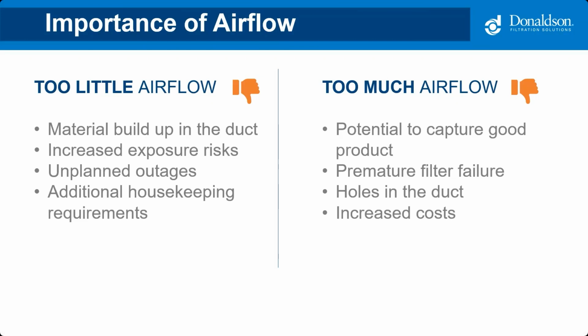Now, if you have too much airflow, you have the potential where wherever your hood is, whatever dust it's trying to suck up, maybe it's going to be sucking too much at that pickup point. It's actually going to be picking up good product. Sand reclaim is a really good example of this. If your velocities and your airflow are too high, you might be beating the heck out of your ductwork and your filter bags and causing premature failure of those and getting holes in your ductwork, and it all could lead to a lot of increased costs.